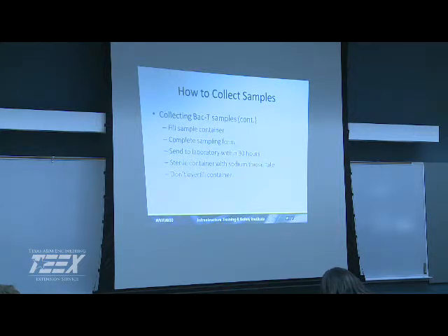It could be, we can have a false negative, because I can have bacteria, pathogens in there, and I can dump a bunch of bleach and I get a negative, but I really had stuff in there, so I can have a false negative. I can also have a false positive. I can contaminate that sample from my cooler, from my hands, from the atmosphere, but it's not really in my water, so that's a false positive. So what we want is, if it's really negative, we want a negative. If it's really positive, we want a positive. And that's how we want to handle it.